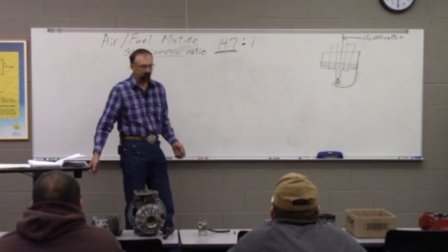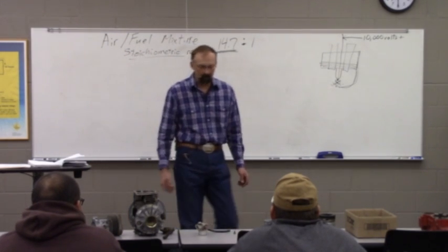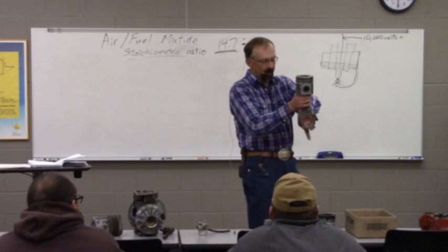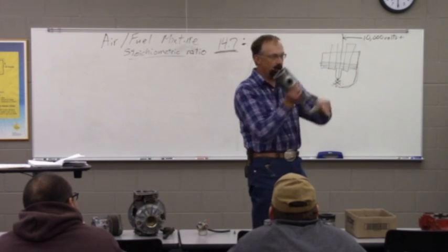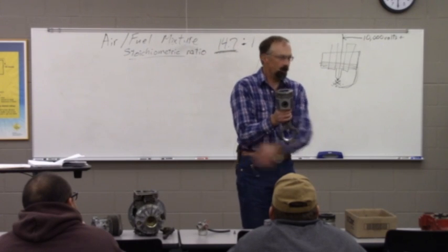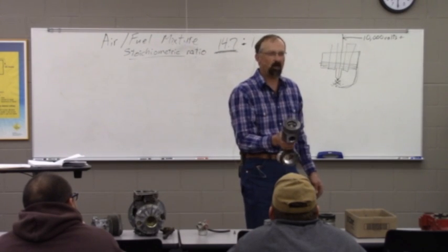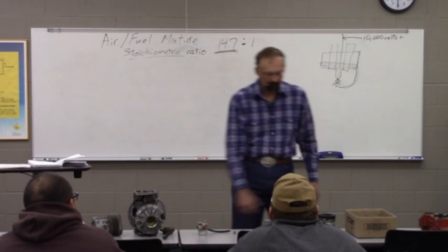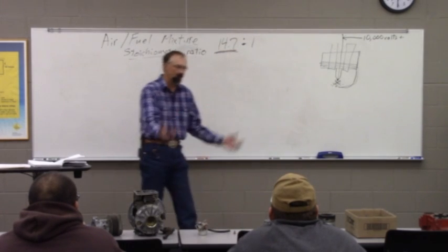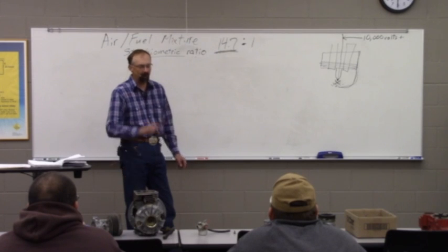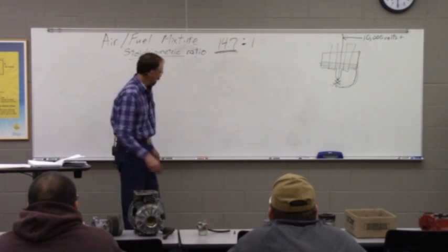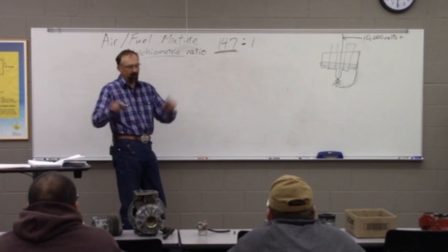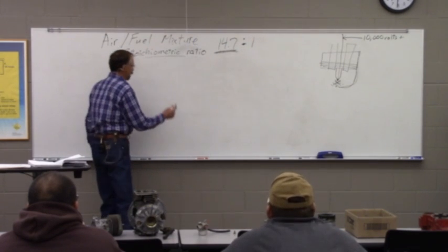And all the modern engines are pumping it. Some of the early engines just had what was known as a slinger. So on our connecting rod, there'd be a little finger down here, and every time it came around, it would dip in the oil that's in the pan and splash it around everywhere, and you kind of hoped it splashed where you wanted it. And a lot of them did a fair job, but definitely not as good for long life of all the bearings as if we pump oil to each one of them. So there again, we talked about our engine block, we talked about how there's passages bored through it, and we're pumping oil to all of those components.